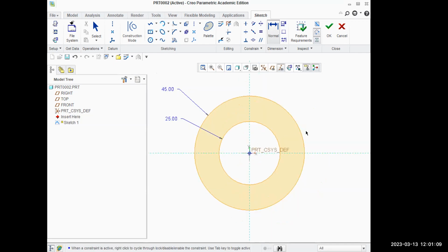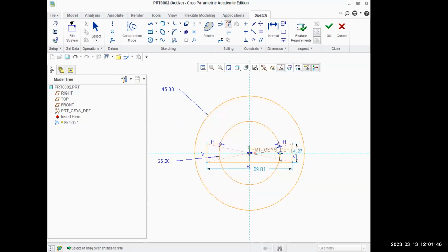So it will regenerate. Now what we have to do is drop 2 slots kind of thing, right? For this horizontal part, I am going to select this center rectangle. As I have reference, I am going to drop this one. Is that clear? Right. Then we can go to delete segment. Okay, still it is not complete. Delete segment. Whatever unwanted portion is there, please select. This is the unwanted portion.